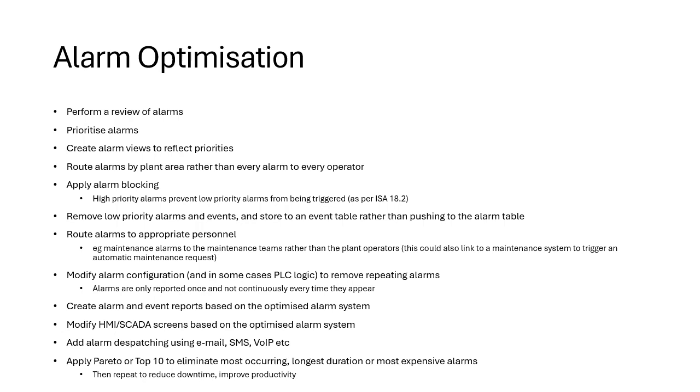Often you only want operators to see alarms which they can actually act on themselves. So in your main control room, you might have an operator that's responsible for a particular area of a plant, and on their workstation, they will only see the alarms which are appropriate to them. And if you're down on the plant itself, if you have the HMI SCADA operating a particular part of the plant, typically you'd only want alarms for that part of the plant to be displayed.